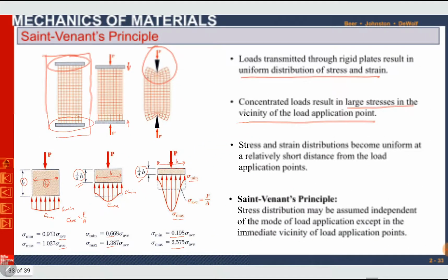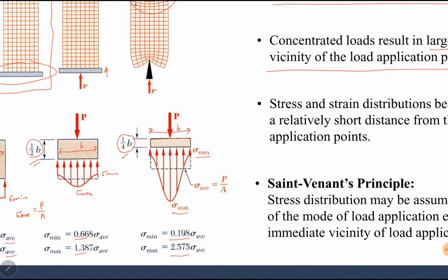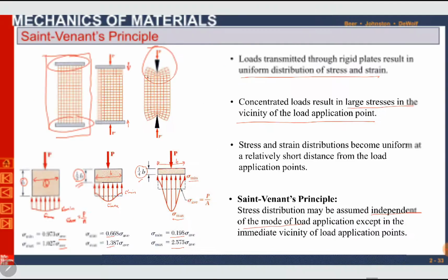Now we have a principle here, Saint-Venant's principle. The stress distribution may be assumed independent of the mode of load application except in the immediate vicinity of the load application point. So immediate vicinities of load application points are very important. Beyond the immediate vicinities of the load application point, the stress is independent of the mode of the load, either a point load or a distributed load. If we move away from the load application point, stress is almost average.